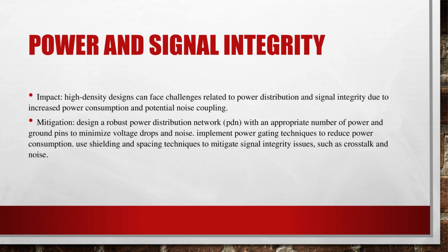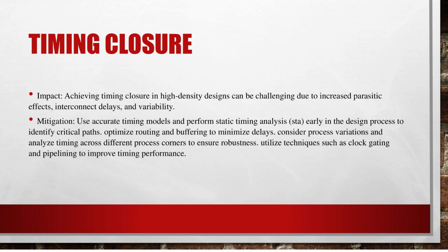The next challenge is timing closure. When we choose high density circuits, the parasitic impact is going to increase. This parasitic impact affects timing, increasing the delay time. So how can we avoid this kind of timing issue? When we choose clock gating techniques, we can switch off unwanted clocks. This kind of technique helps avoid unwanted noise and interference, so we can improve timing issues.